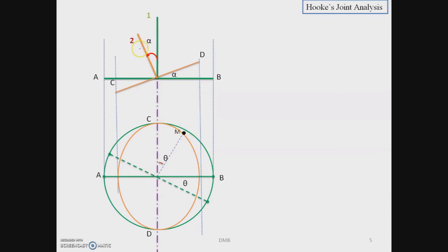The true angle turned by shaft 2 will be viewed along its own axis. That is, when we see the rotation of the fork CD along the axis of shaft 2, we will see that CD is actually traversing a circular path, and the angular displacement of fork CD will be different than that of theta.